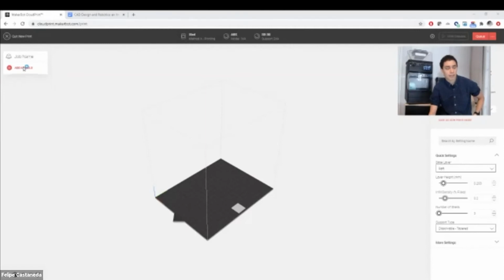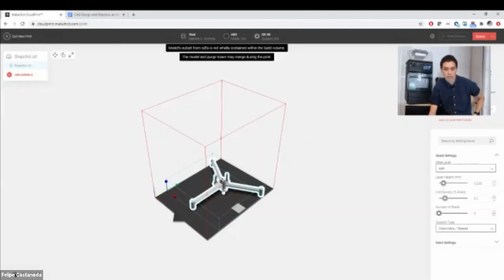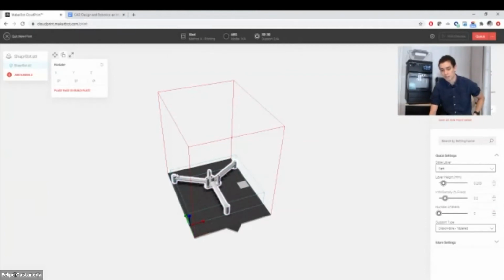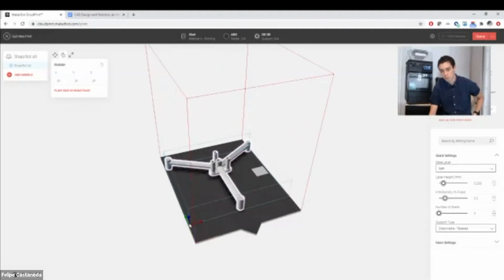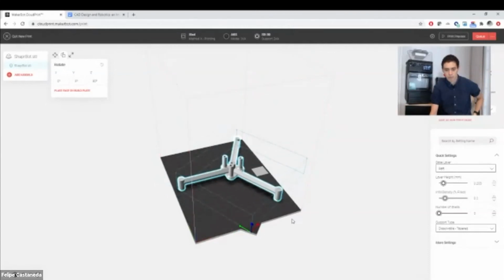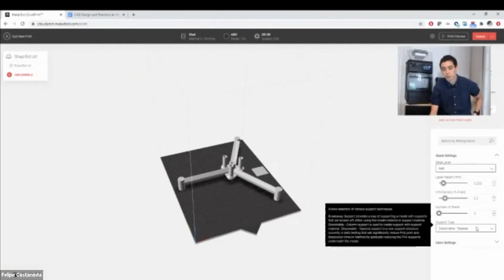And while I'm at it, the origin itself, especially after the file has been exported, is fairly straightforward to change here. As you can see, the origin access point is now reset, and it's unique to the part itself. It's actually taking the bounding box of the part and putting the origin point of this body in one of the corners of the bounding box. In this case, I'll just rotate my part a little bit so that it can fit nicely in my build plate. There we go.